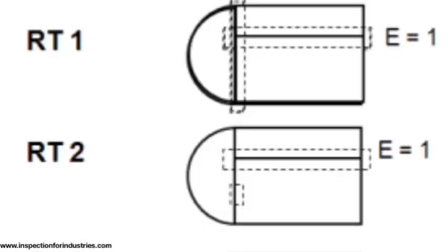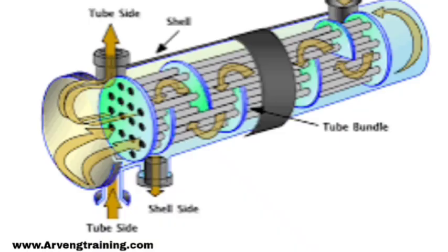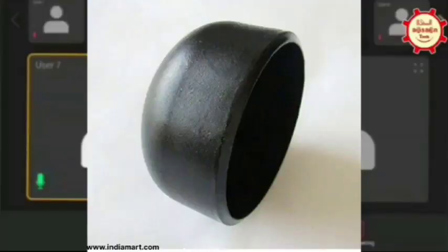In this area, I have some clarification because my shell is a seamless pipe. Under the pipe, both ends have a standard pipe cap. In the shell itself, one circumferential seam will come, because we have internals that we need to fix and then we do the circumferential seam.